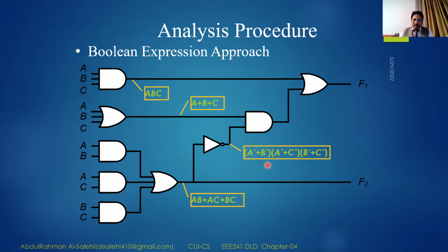What was that? The multiplication of 2 bits, the ANDing, is converted to ORing. And the ORing is converted to ANDing between them. Again, for the other one, the ANDing, instead of the dot between them, it will become ORing or plus. Again, if we come to the ORing one here, what will it be? It will be the ANDing. And so on for BC as well.